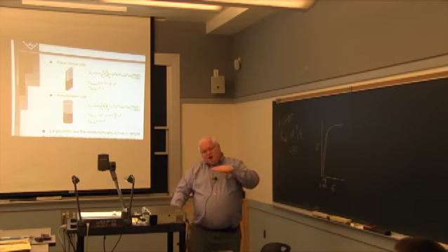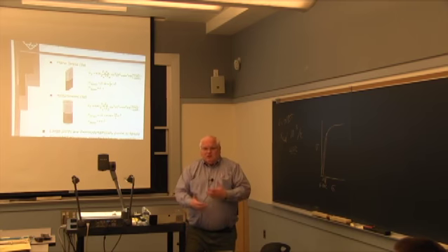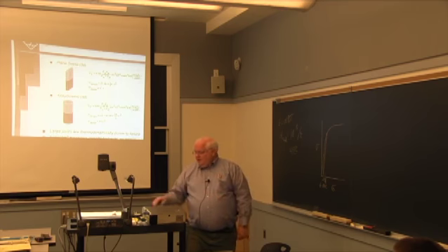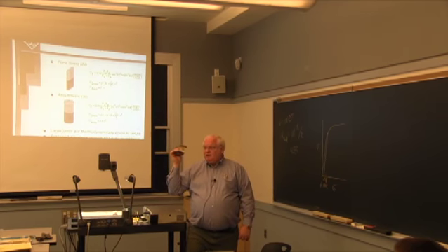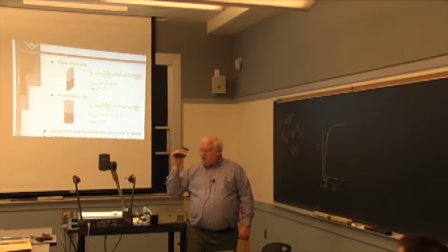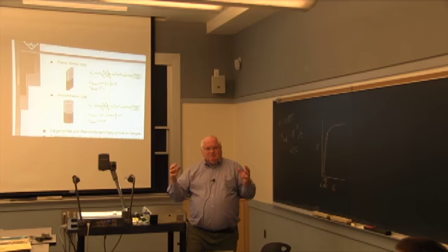But in fact, if you actually get only a 10% bonded joint, and let's face it, what's the stress on that aluminum at the bottom of a cooking pot? Okay, there's not a lot of stress compared to the area of bonding, right? You actually want porosity at that interface. They actually want porosity in the bond coat of these things to a certain extent, because what has a better ability to absorb strain than empty space?